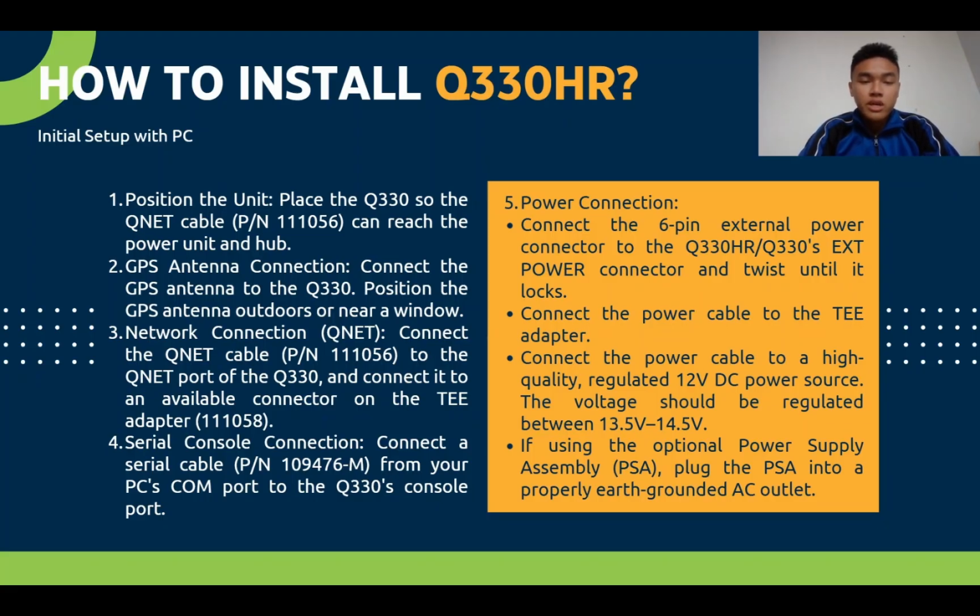Network connection QNet. Connect the QNet cable to the QNet port of the Q330 and connect it to an available connector on the TEE adapter. Serial console connection. Connect a serial cable from your PC's COM port to the Q330's console port.